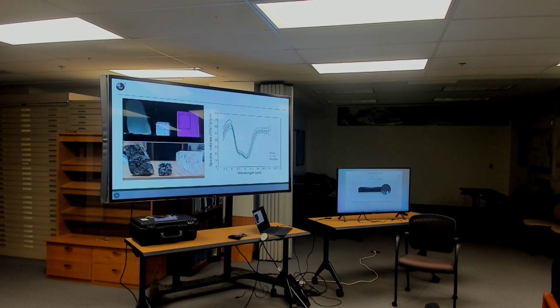The advantage is these things can be operated at room temperature. The kind of photon detectors that I've been speaking about in the thermal part of the spectrum, you have to cool them to cryogenic temperatures. And to cool them, you need a fridge. The fridges are noisy, they vibrate, and they use a lot of power. So putting them on spacecraft is something that people maybe don't want to do, right? But these things just operate at room temperature without any cryogenic cooling, which means these things are cheaper.